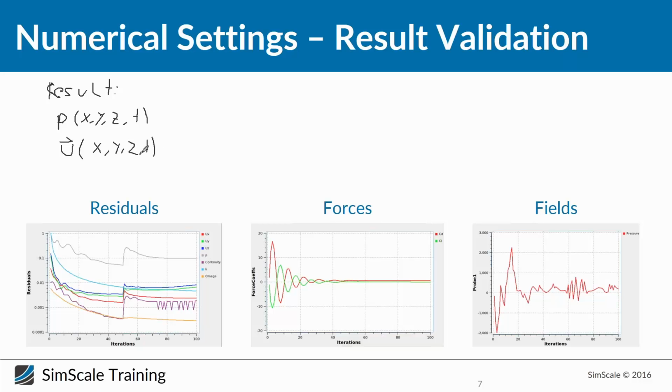That looks very abstract, but basically it's easy to understand. A fluid flow is completely described when I know for every point pressure and velocity. All other quantities, which we for example used during the last session, like turbulence kinetic energy K or omega, are just additional help quantities, which are physically not necessary because pressure and velocity describe the fluid flow completely.